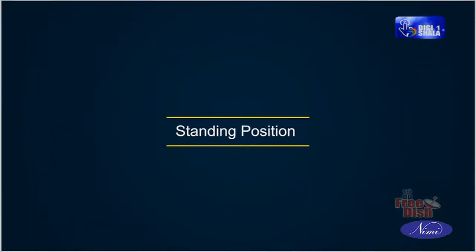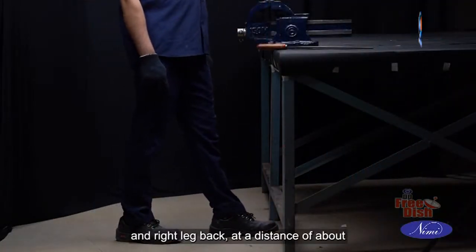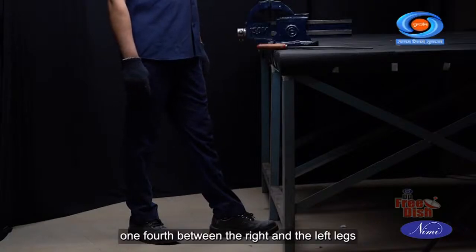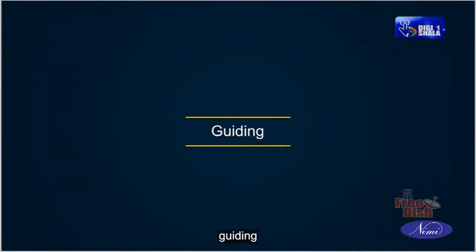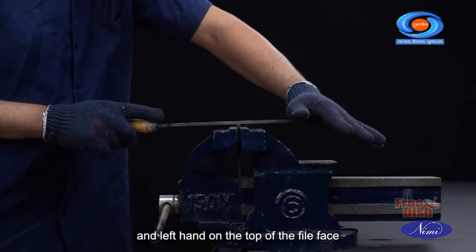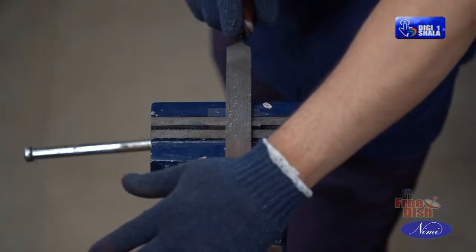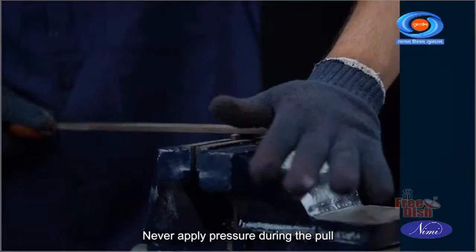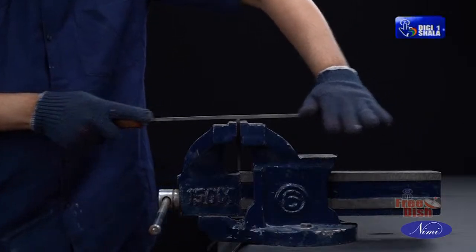Standing position. Left leg in front and right leg back at a distance of about 1 foot between the right and the left legs. Guiding. Right hand on the file handle and left hand on the top of the file face. Handling the file. Never apply pressure during the pull or draw stroke.